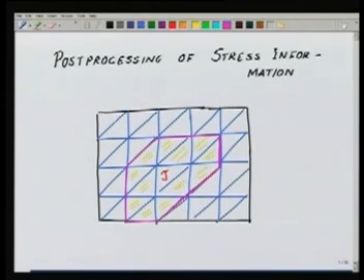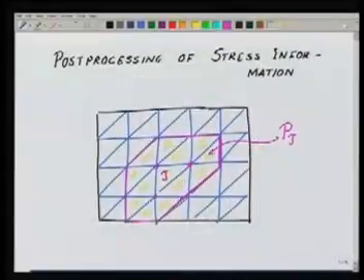So you have to understand that here I have taken all the elements which share either a node or an edge with the given element. The set of all these elements, including this element, forms the patch which I have marked with this line. It forms the patch p tau. So this is the one element neighborhood of the element tau. Given this patch p tau, now let us see how we can construct a better stress information in the element tau. Remember, our goal was the element tau.